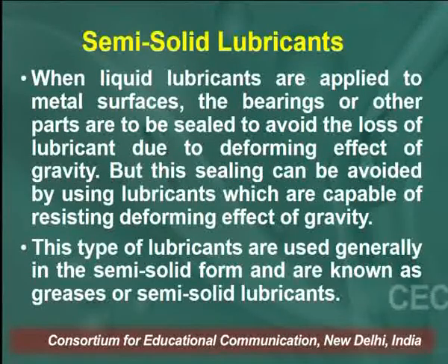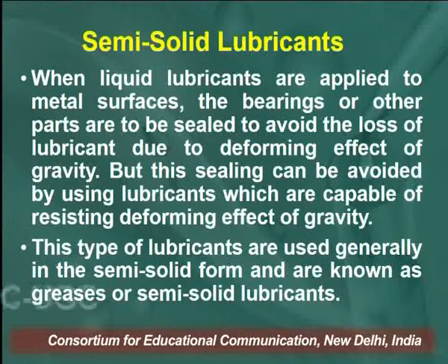Now moving on to semi-solid lubricants. When liquid lubricants are applied to metal surfaces, the bearings or other parts are to be sealed to avoid the loss of lubricant due to the deforming effect of gravity. But this sealing can be avoided by using lubricants which are capable of resisting the deforming effect of gravity. This type of lubricants are used generally in the semi-solid form and are known as greases or semi-solid lubricants.